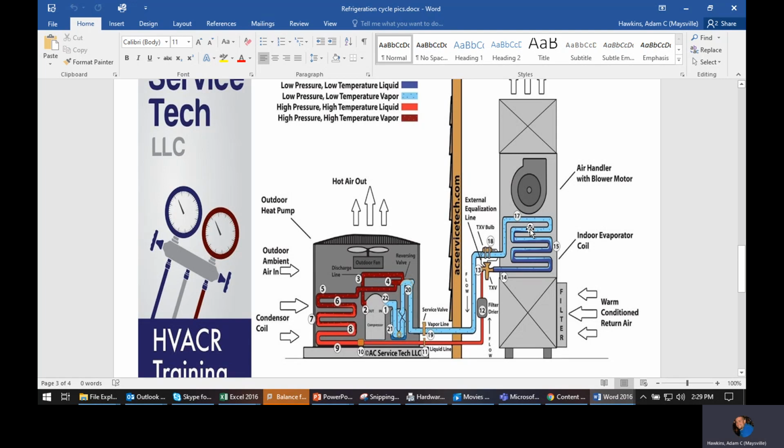Think back to our water bottle lab, where we had the one that was frozen, that was thawed, and then we had the other one that was already thawed, but it was cold. They both did work and they both attracted heat, but the one that was going through the latent attracted way more than the one that was in the sensible. The one that was already water, 100% water, even though it was cold, it didn't pick up near as much heat. So sensible heat just doesn't have a lot of ability to catch heat, but it is necessary.